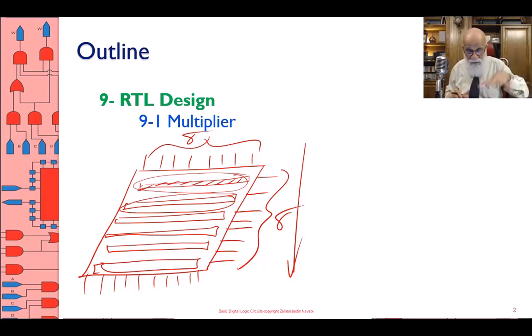Conceptually like this. This is not going to happen like I'm saying it now. But the fact that instead of using 8 adders, let's use one adder, and instead of propagating the results, let's clock them into a register, and then let's reuse that same adder. That's a good thing. Actually, what we did for our serial adder before, we did something like that, right? Because there was this serial adder that we were building.